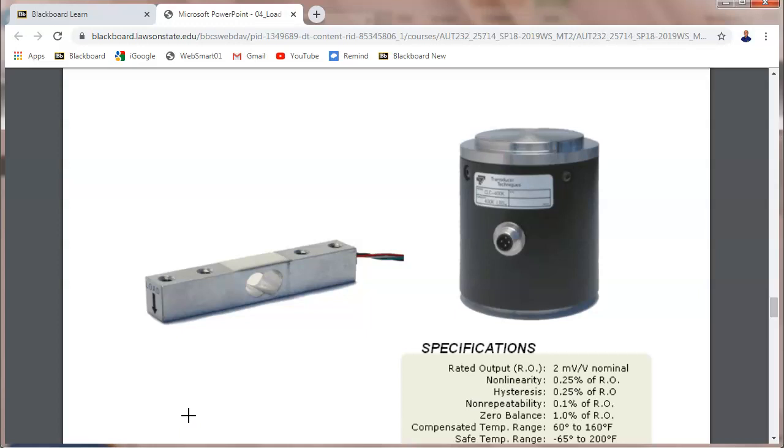So if you ever have to run into scales, what you'd do is you'd come up here and you'd set a 0, and then you'd put weight on it, and then we would come over here and it would start off with a slant like this. Then you'd put weight on it and you'd adjust it. Well, as soon as you adjust this, what did you just change? You changed your 0. Well, that's what you had to do. You had to set 0, then you had to come up there and put weight on there, and then you'd set 50,000 pounds, and then you'd take it off and go back there and redo your 0. And it took about 4 different times to get the span set right.